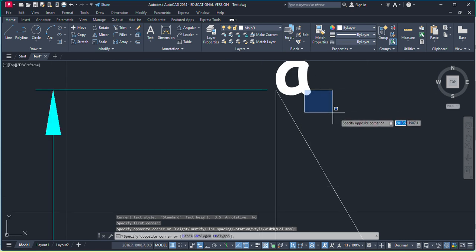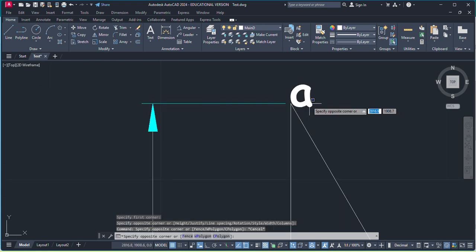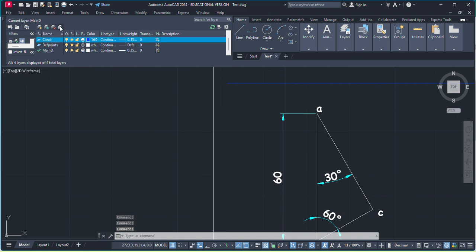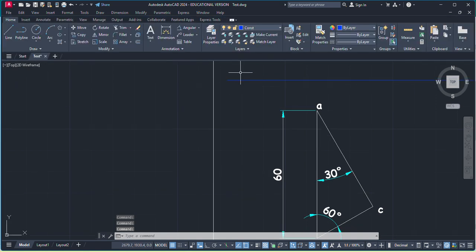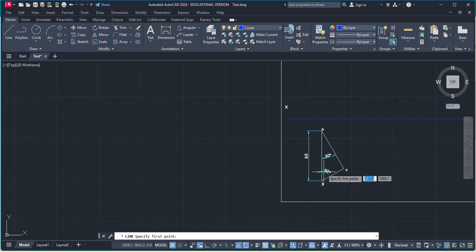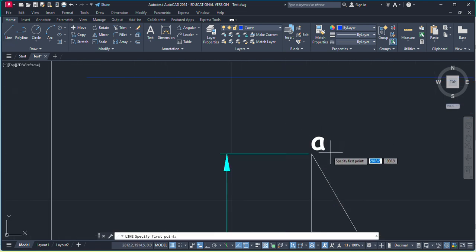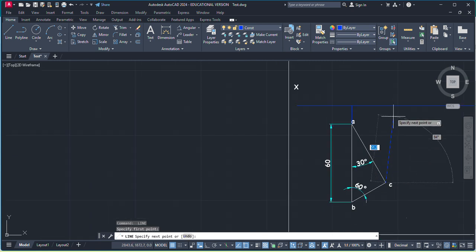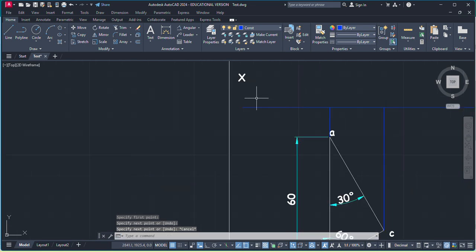Now again, this is a set square, a triangular lamina. So we will have a straight line in the front view. Again, these 2 points A and B are on the same vertical line, so I'm just using a single line from here. So this is the first point, this is the individual one. So from here draw a vertical line, intersect here. So this is going to be a C dash.